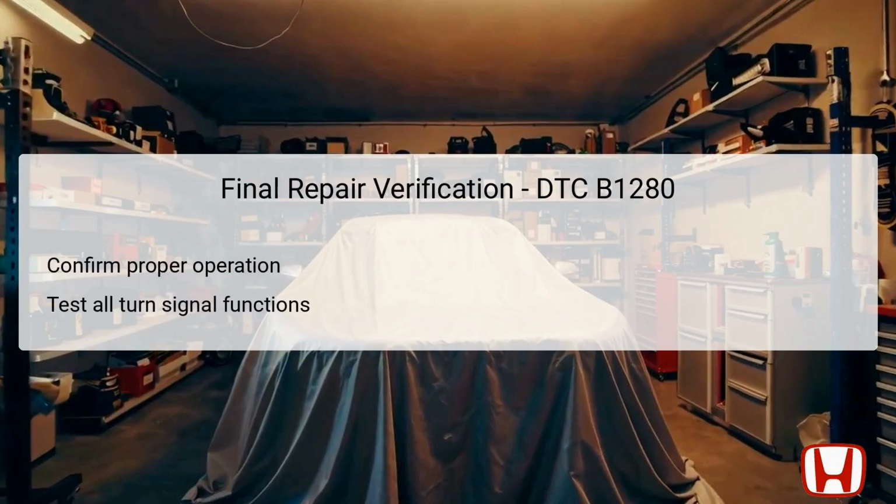Upon completing repairs related to DTC B1280, it is essential to verify the integrity of the work. Full functionality of the turn signal system must be confirmed by testing all modes of operation. Engage the turn signal switch to the left and right positions, ensuring that each side illuminates correctly without faults. Additionally, check for correct feedback on the dashboard indicators, verifying that the signals correspond accurately to the user's input.